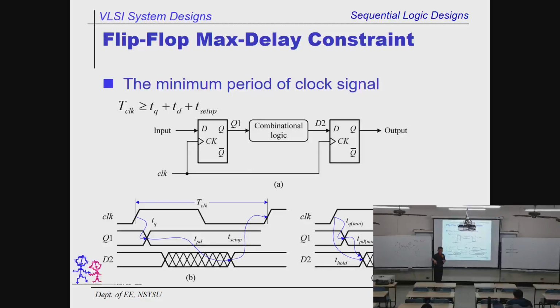Right now in this course, all the students only carry out the middle combinational circuit: the adder, shifter, register, multiplexer, multiplier, this kind of thing. It's all combinational. But you gotta have flip-flops to help you synchronize everything at the input and at the output. This is the basic rule you have to follow. That's it. This is the basic timing equation that I hope my students can remember.